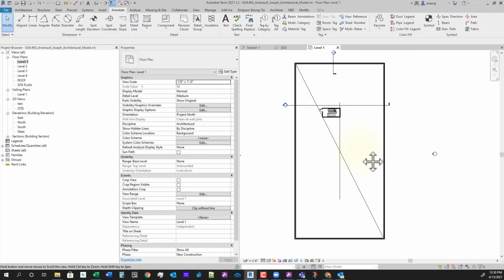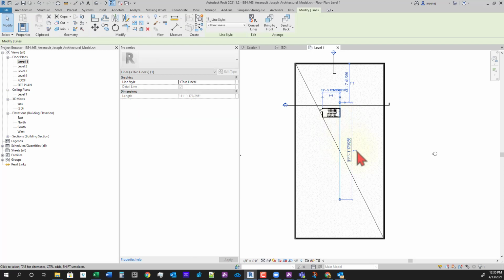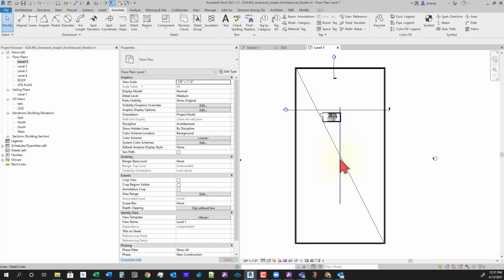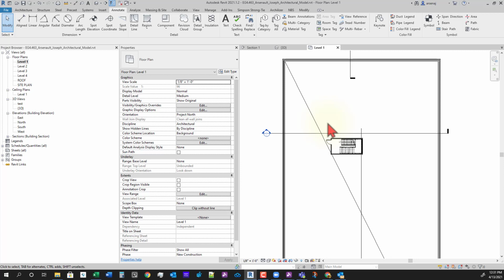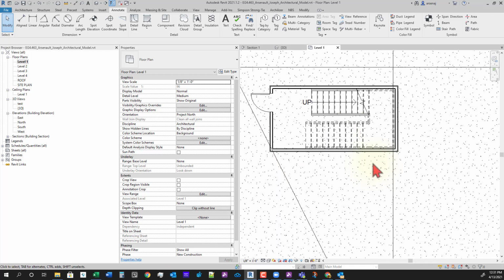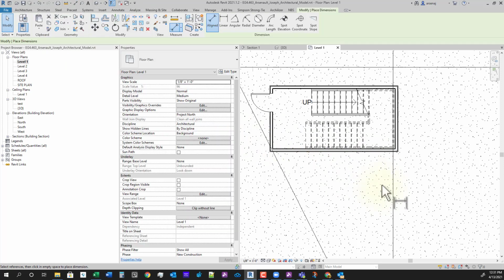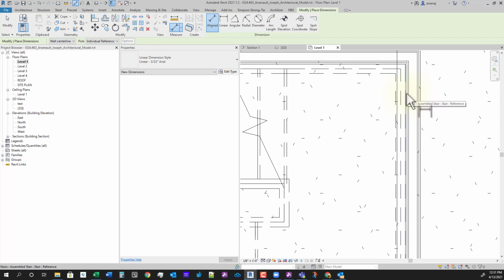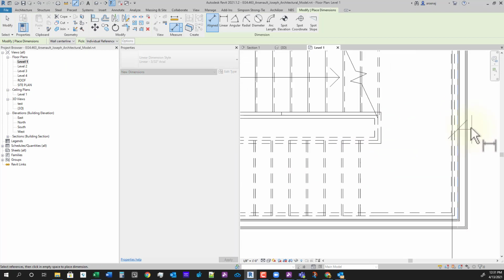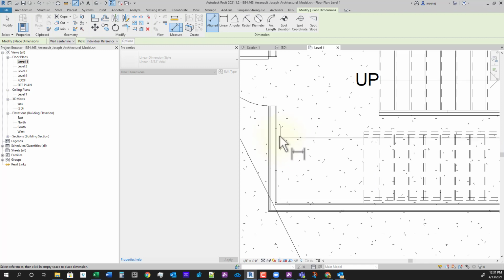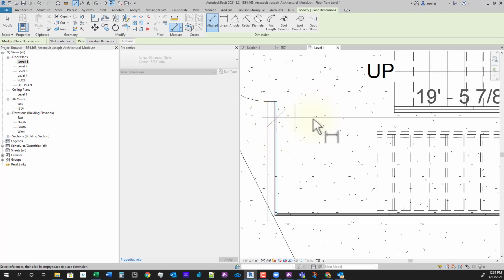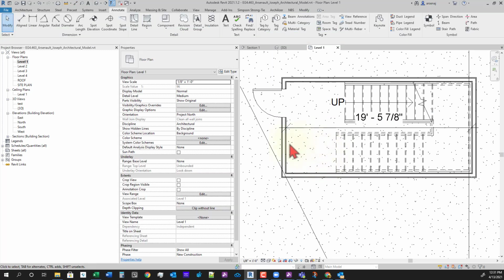for that detail line. So now we have a 111-foot line that will signify half the distance of the diagonal for the stairs to be located. So the next thing we'll do is go to your dimension, hit DI for dimension, or go to your Annotate and hit Align Dimension. Let's grab the inside face of our stair on the right to the inside face on the left, and let's just make that an even dimension.